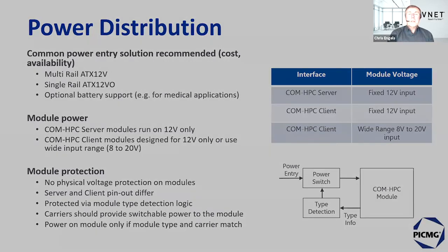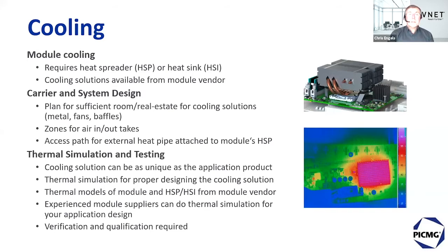The cooling is a different area and is a very wide field. The specification specifies a heat spreader. Heat spreaders are good if you have a reasonable amount of dissipated heat, say up to 40, 50, 60 watt range or so maximum.